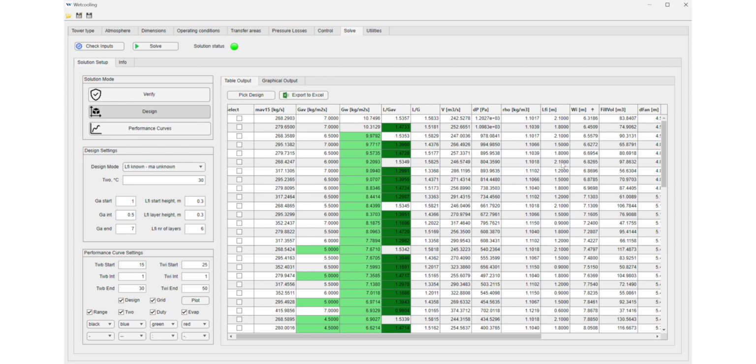So the final step of the optimization requires the user's input, because we cannot incorporate everything into the software. If you use the pressure drop and the volume flow rate, you can specify a fan. If you specify a fan using these three parameters, usually you require the operating point in terms of the volume flow rate, the pressure drop, and the density of the air at that point.